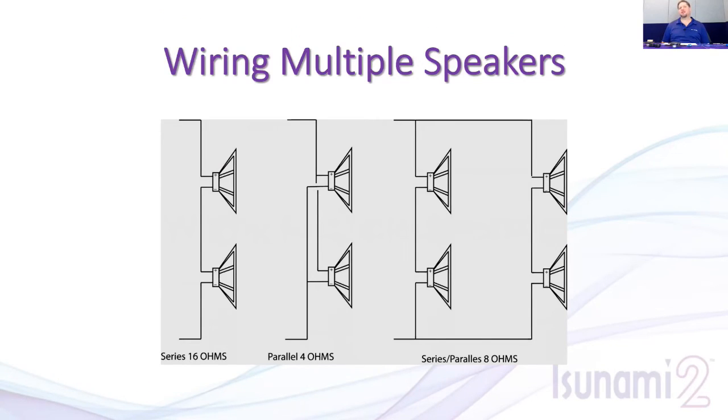The one thing I forgot to mention is that when you are doing a series, you want to make sure that the plus and minus of the different speakers are matched up, so that when they work together, they're both moving forward when that power comes through. Because if you have one doing the opposite, then the 2 speakers are actually going to cancel themselves out, kind of the same way we saw when we didn't have the baffle on our speaker.